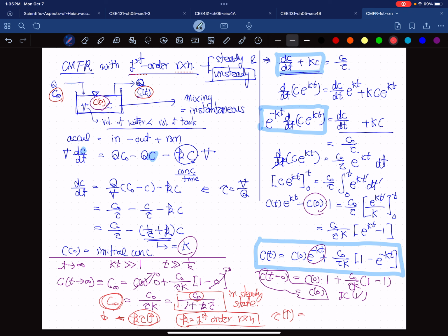And you know that tau was given as solution volume divided by flow rate. So if your effluent concentration is relatively high, then the easiest way is to slow down Q, then tau, the hydraulic retention time, increases, and then your denominator increases, and so the effluent concentration decreases.